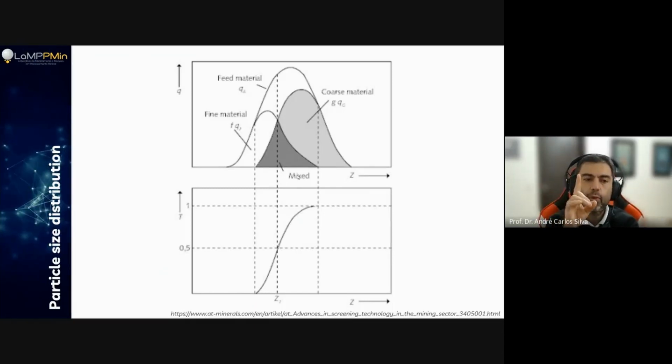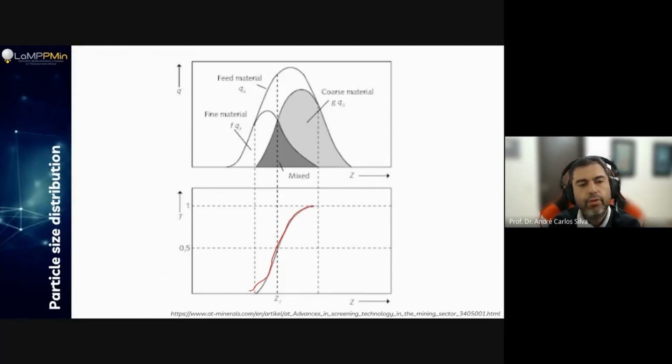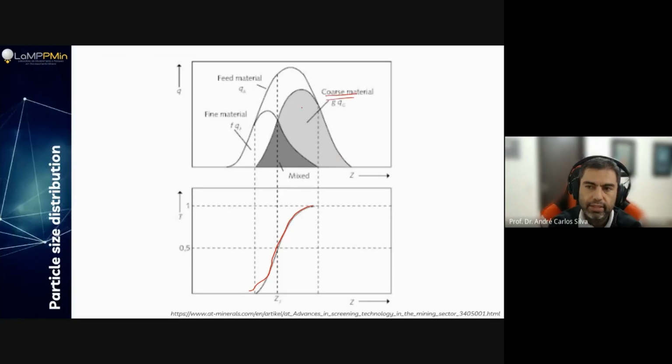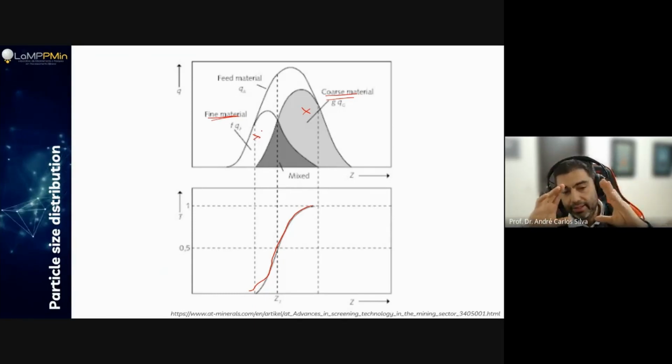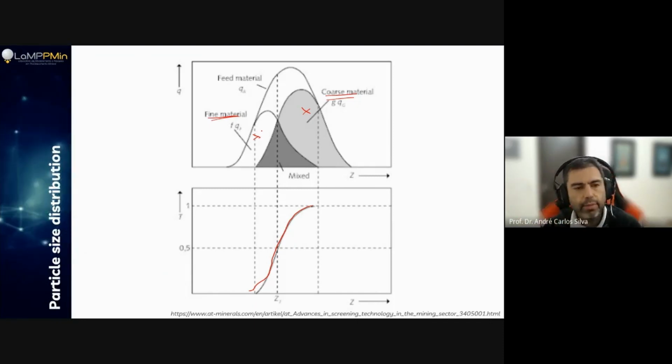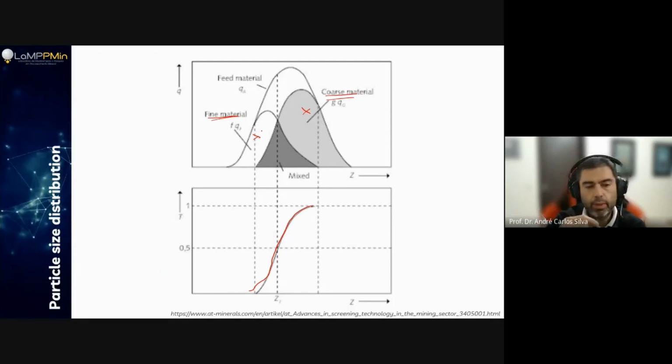So I'm going to have one curve that's actually a misinterpretation of two other curves. And that's what I'm telling you in here. So take a look at the particle size distribution. You're going to have something like this. Yes, over here. What information can you draw from here? None. You're going to take a look and say, oh, okay, this is my material. But actually, I have this coarser material in here, this fine material in here, and you're seeing the two waves together. So I can't have any good, reliable information from that, because it's missing one. It's missing what? The histogram.